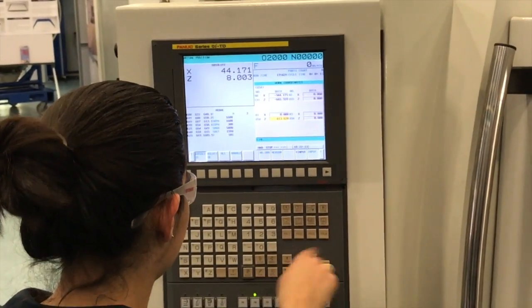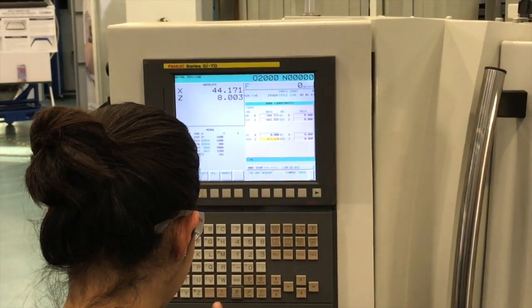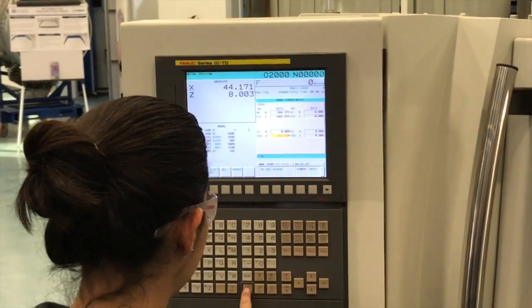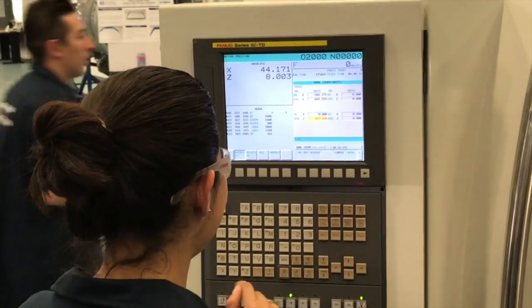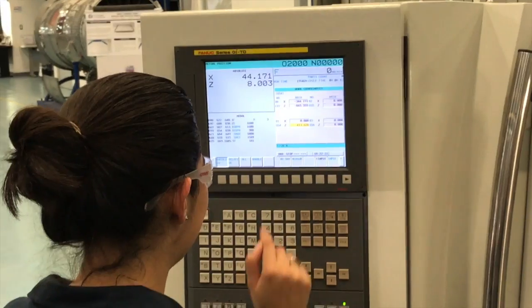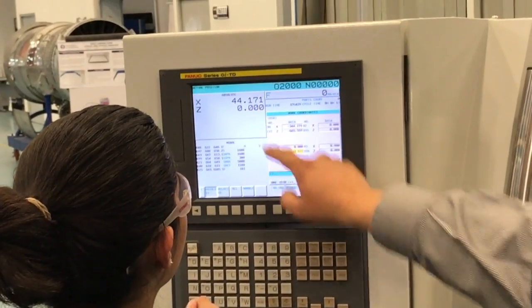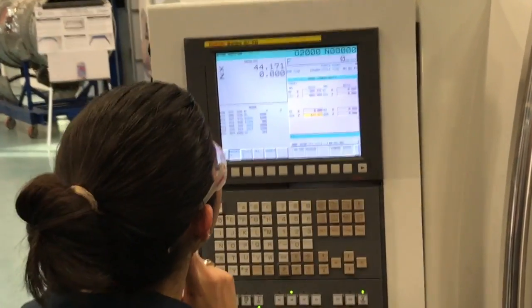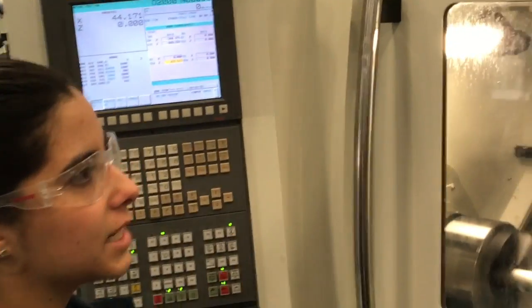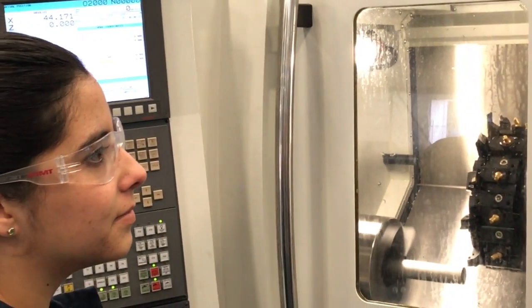You have to move the tool above the outside diameter of the raw material. For that, the Z button should be pressed and then type 0.0. This must be verified in the screen. This procedure can be realized only once because the tools are adjusted with the tool setter.